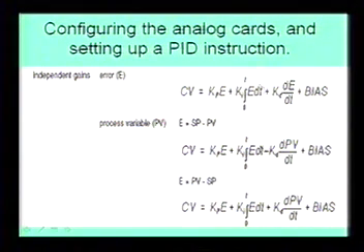I'm not trying to tell you to solve the integration of the error or make a complex instruction, or go study calculus and learn controls. It's not necessary. All you need to do is drop the PID instruction in there, know what your proper process variable is, know your control variable, and make sure that you can walk up to it manually, open the valve to 50, 60%, and see that the system is somewhat stable. Then you know that your process engineers have designed, or maybe you've designed, the proper flow in, the proper flow out, and you've got the right size pump.